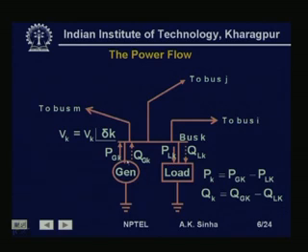We can always take the algebraic sum of these two, that is, subtract the real load PLk from the generation Pgk. Then there is a real power injection into the bus equal to Pgk minus PLk. Similarly, we have a reactive power injection Qk equal to Qgk minus QLk.